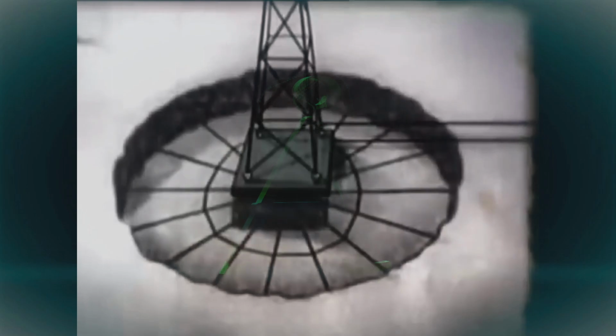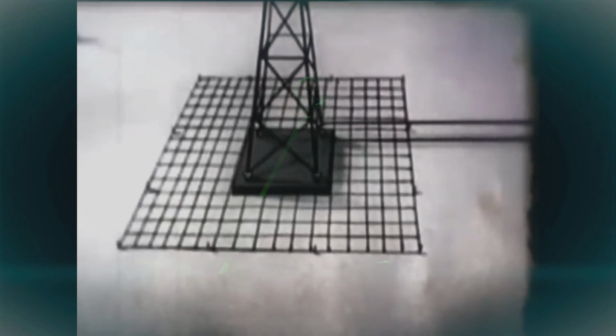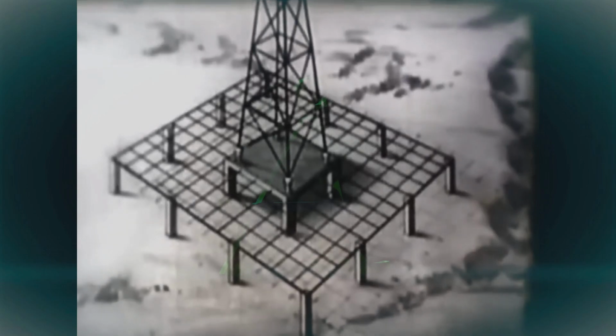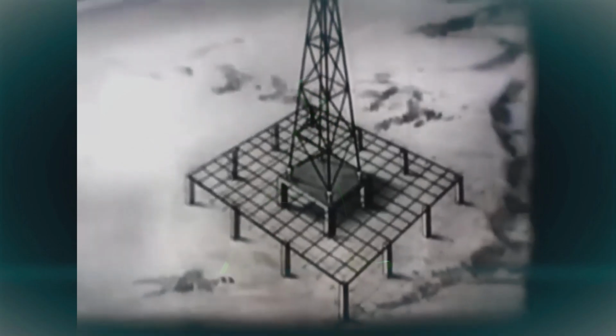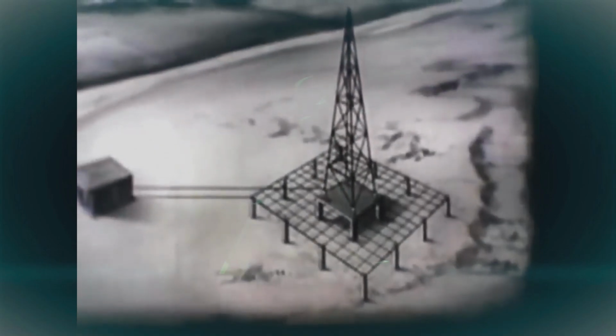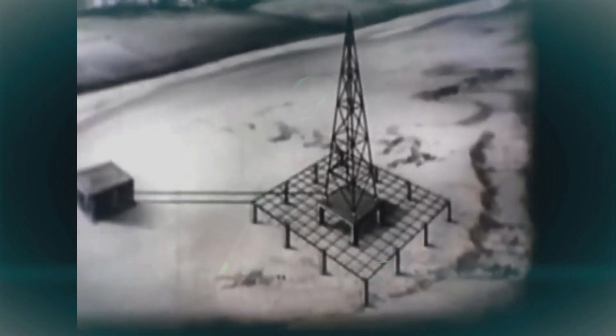In drier regions, a system of conductors installed at the base of the tower may be required. These radial conductors are connected to a common point at the base of the tower. Sometimes on some installations, an additional system of wires lying on the ground called a ground screen is used, thus forming a more effective ground. Where it is not practical to bury conductors, a network of wires called a counterpoise is built above and insulated from the ground. A transmission line transfers power to the antenna, and herein lies a final problem.